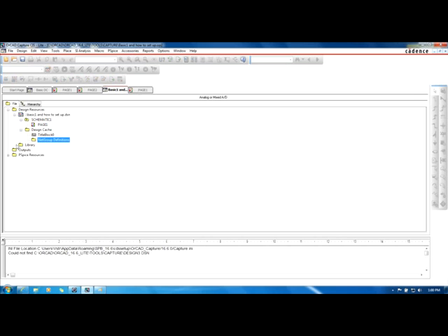Net group definition, that's not part. Library, parts being used. Outputs. Okay, the outputs are going to be important for doing a simulation. It'll create the outputs, but if you were to give somebody this .dsn file, and you had specific things you want to do with the probes, a probe set and everything, then you would want to have an output file that you send with it, which will be generated out of this by the program.